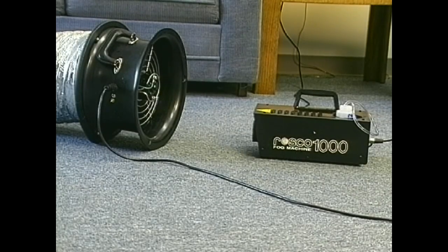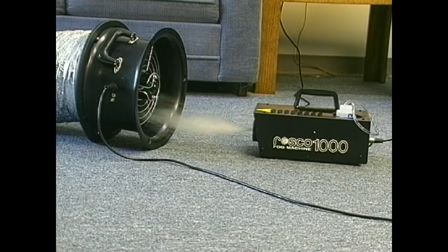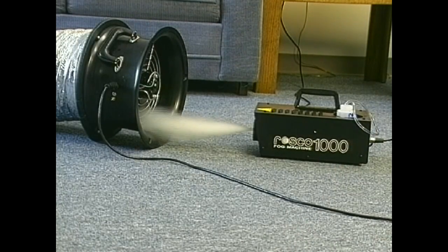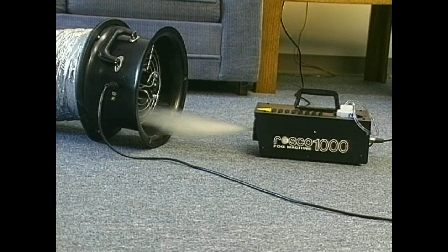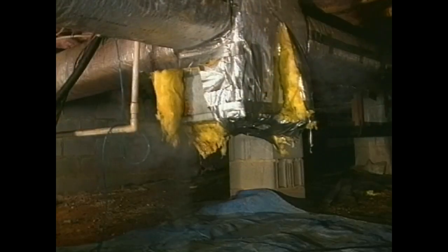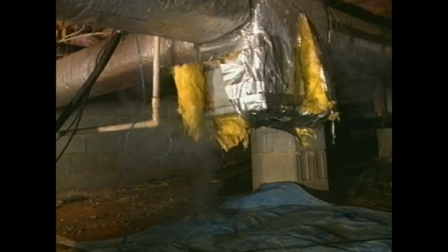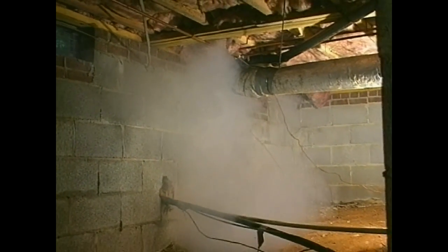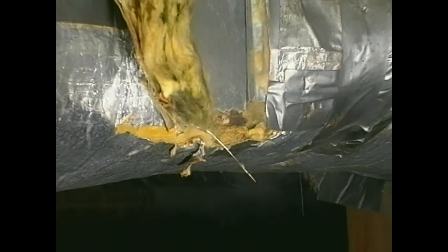Finally, one of the most effective ways to find leaks in the duct system is to use a theatrical fog machine while pressurizing the ducts. With the registers and grills temporarily sealed off, the fog machine is used to inject a non-toxic theatrical fog through the duct blaster fan and into the duct system. The theatrical fog is pushed out of the leaks in the ductwork, visually demonstrating the location and extent of the duct leaks. Use of a fogger helps crews find hidden leak sites in attics and crawl spaces, and it makes a dramatic presentation for homeowners and builders.